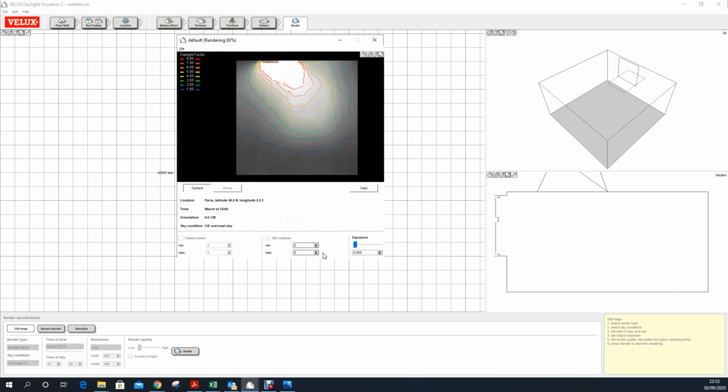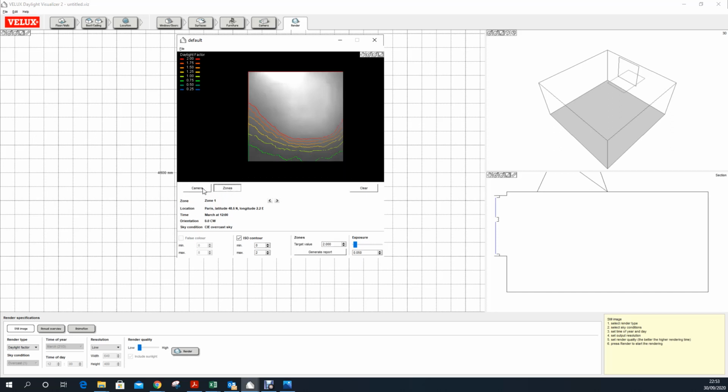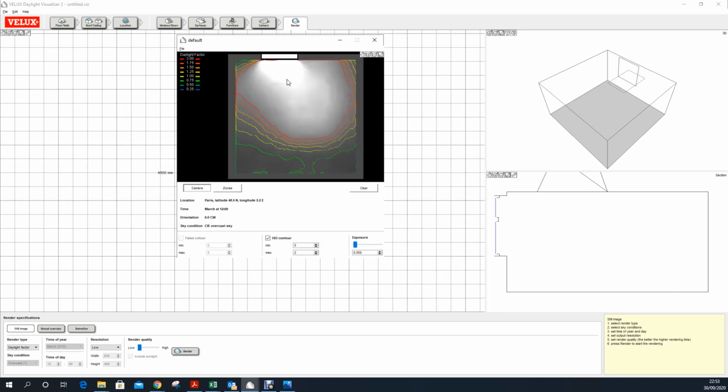So what you can do is what I was trying to do, third time lucky, is you can set the max daylight factor. So in our case it's 2, so you can see for the different living, or it could be 1.5, and you can also look at the different zones, so you can get an idea then about how achievable the average is, essentially. So it's actually very useful in that way.